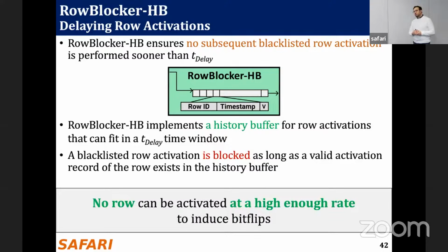I see. I thought that maybe adding one bit that stores, when you reset the counters, the information that it should be blacklisted for another epoch as well. So basically, you want to extract the list of rows that are blacklisted in that epoch and keep them somewhere. Yes, or just add one bit. One bit to where? In every counter. Okay, so okay.